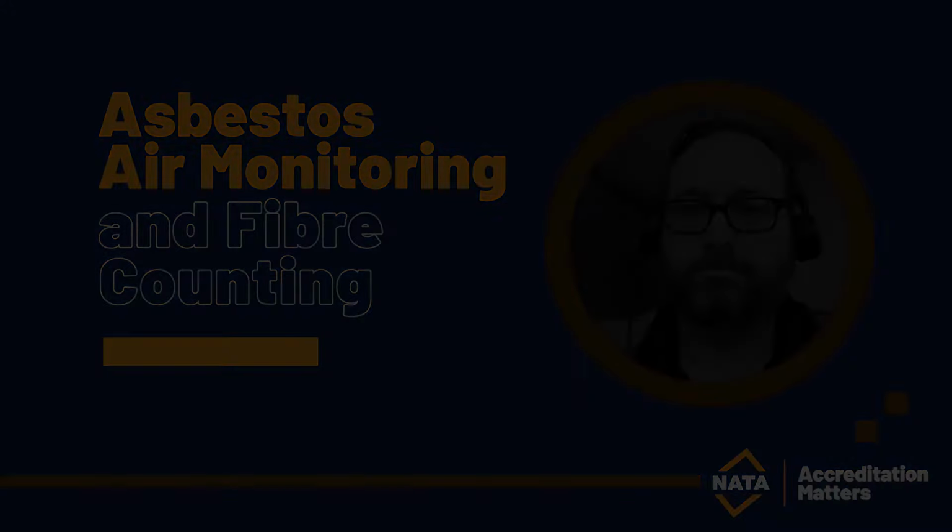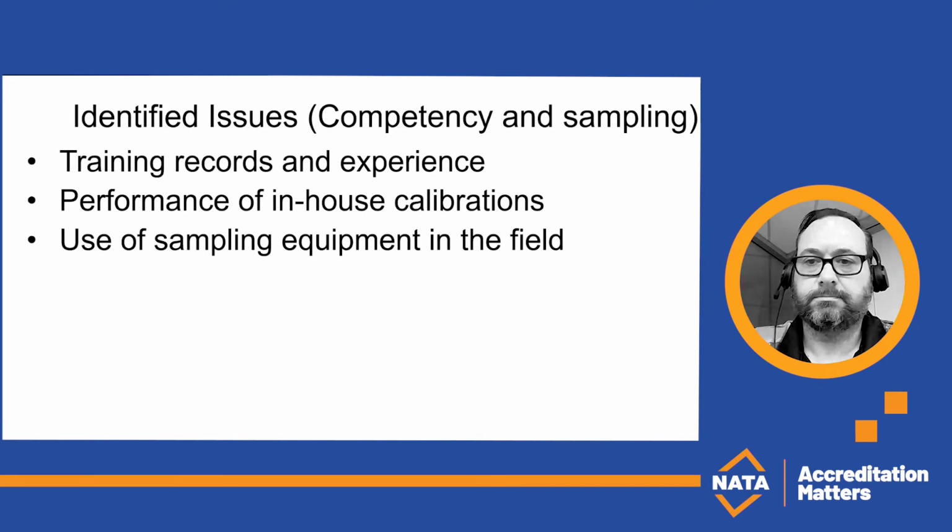So the use of sampling equipment in the field. Are the consultants who are out there sampling understanding the parameters of where pumps need to be placed, how pumps are placed, how equipment is set up, the desired flow rate to achieve certain volumes, and looking at flow rate variation criteria, obviously 10% for asbestos, for voiding samples. And field sheets and chains of custody, really critical that they're filled out properly. And if samples are being submitted to a laboratory, that there's an accompanying COC.